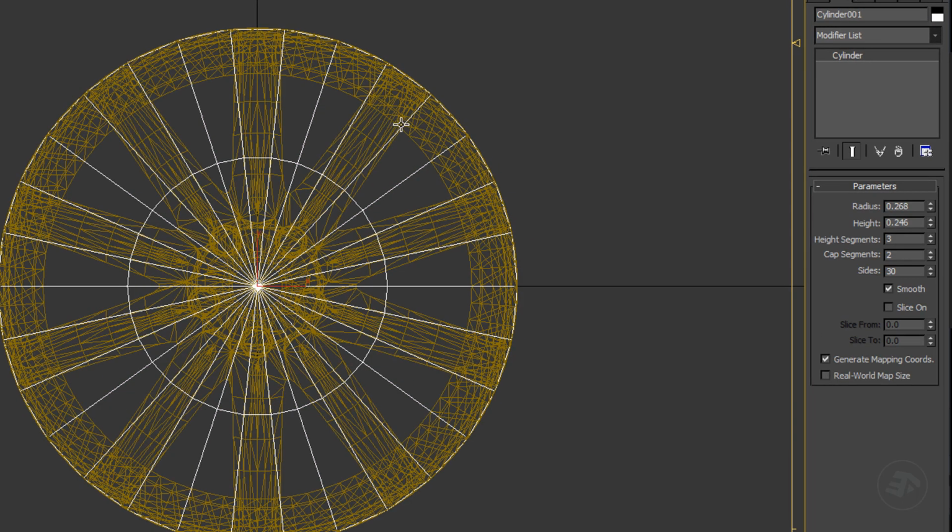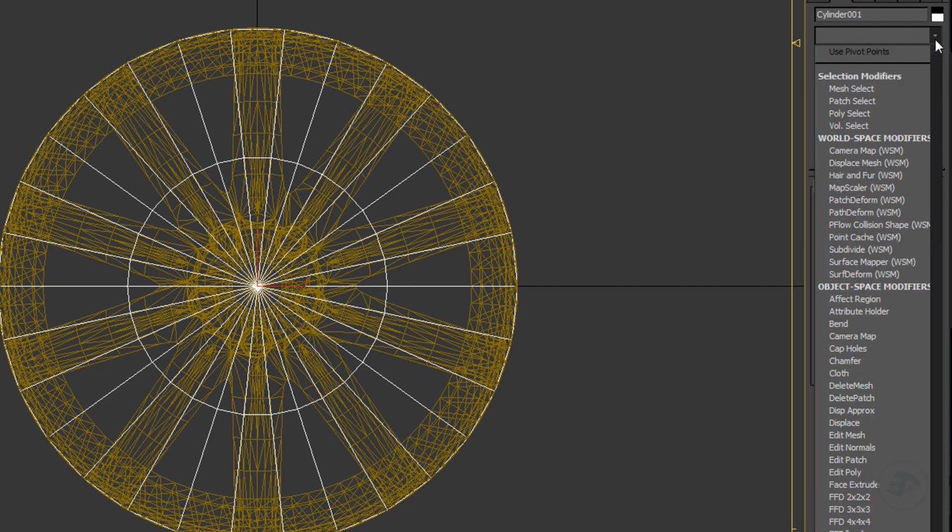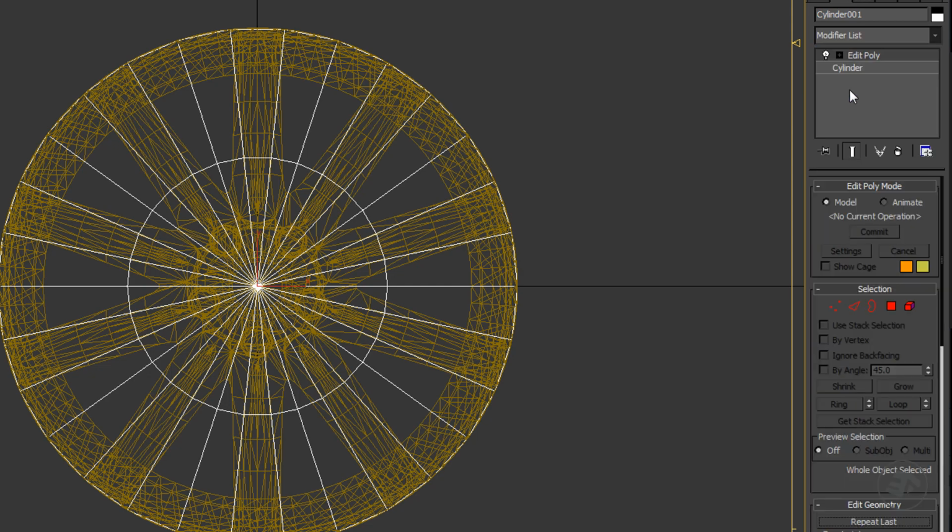As long as the cylinder stays in its logical state, we can change any of its attributes. However, once we add Edit Poly modifier, those values become permanent. We cannot return back and change any of them. The built modifiers in the stack are dependent on each other. 3ds Max does not support history rollback or logical attributes editing in polygons modeling. Only CAD modeling supports those features.